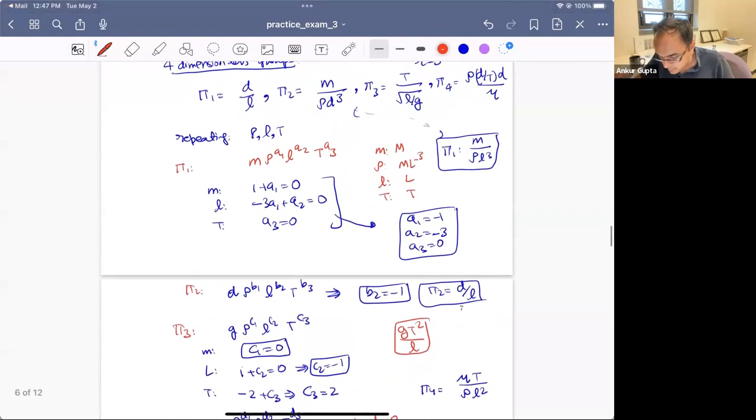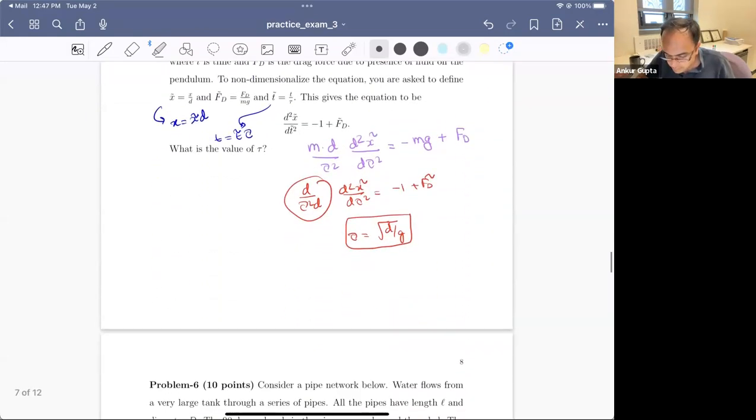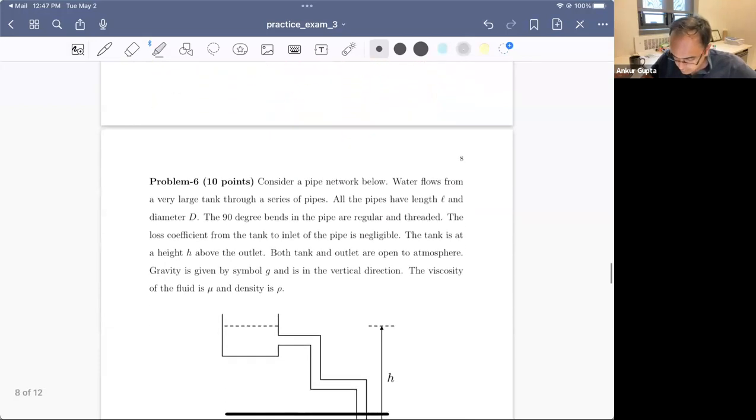But here you can see we have a sort of buoyancy factor almost, mass by rho d cubed here, a Reynolds number coming here, some sort of a time period based on without the drag coming here, and the ratio of lengths coming here. So it's just good to appreciate some of the numbers that you're getting. Similarly here, time is coming out to be the right unit, just to sanity check. All right, so let's keep going.